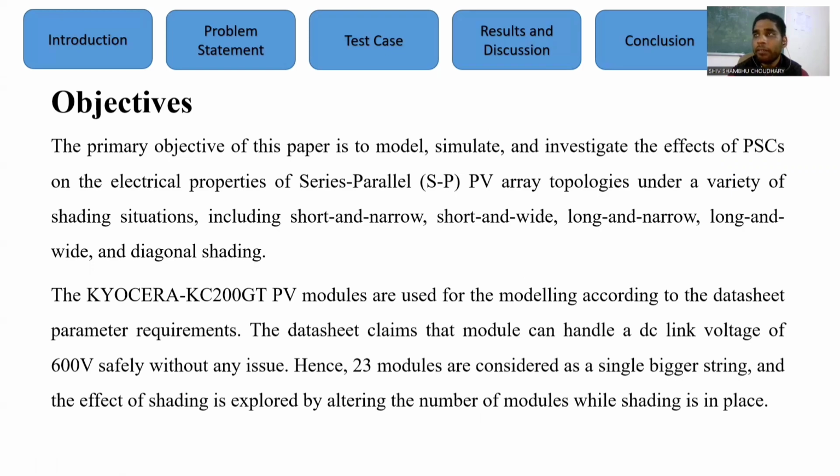However, if they are purely connected in series, the output voltage of a series connected photovoltaic string will be too high to be connected to the grid connected inverters or energy storage device. Hence, to overcome this problem, the modules are linked together in series parallel configuration to derive the required amount of power from the system. The challenge in front of us is now to develop the PV characteristics similar to those of the photovoltaic modules in order to monitor and collect the maximum amount of energy from a solar string or array.